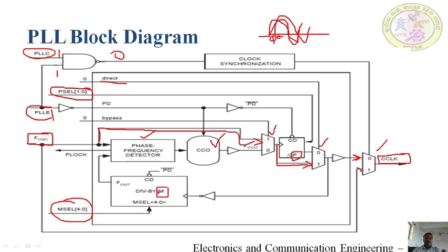And here the divide by M looks like a complicated one and confusing. So actually this is the multiplication to the CCLK, because the CCLK formula, you know, CCLK equals M into FOSC. So here this is the divider for CCLK, so definitely it's a multiplier for FOSC. It's a feedback loop, so it must be divided by this CCLK, then for this FOSC it becomes multiplication.